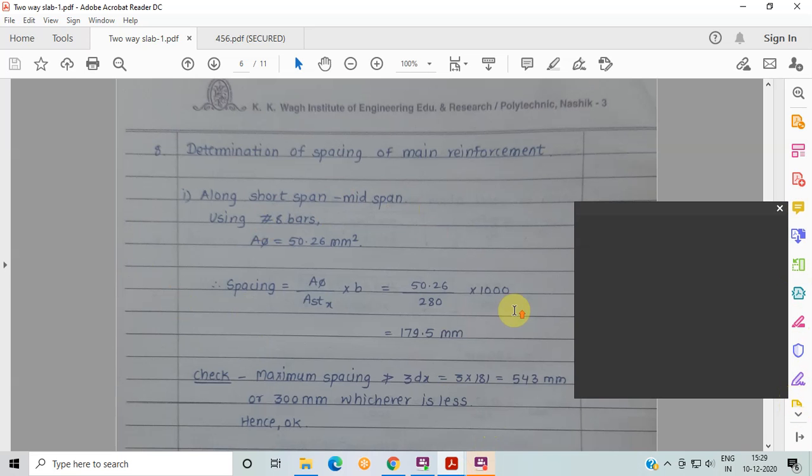Already we have used table number 91 to calculate the bending moment. Here, in Annexure D, the details of torsion reinforcement are given. By using these clauses we are using this equation: AT is equal to 3/4 ASTX. Now 0.75 of ASTX is required, not provided, is required.